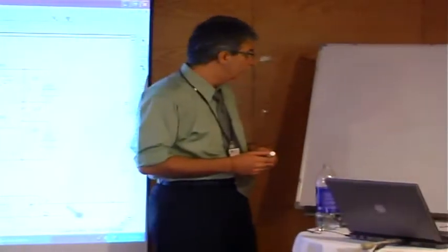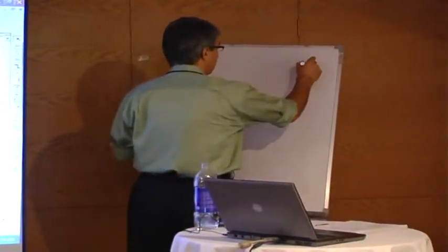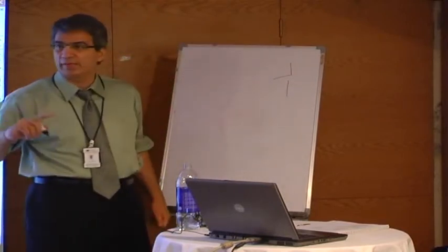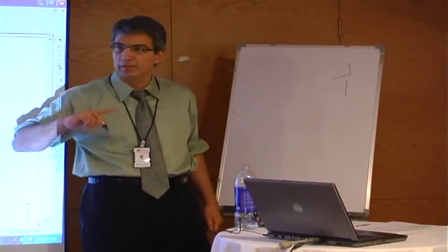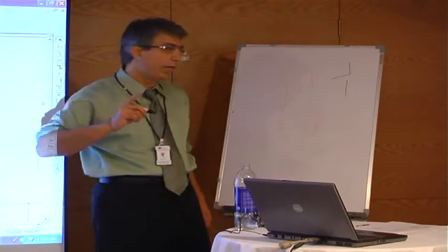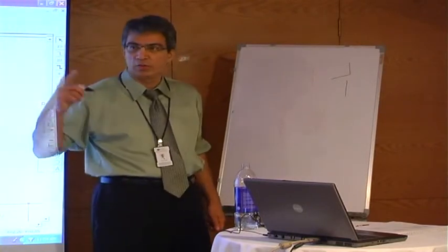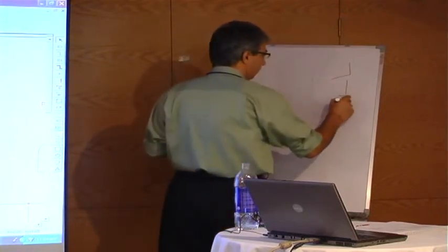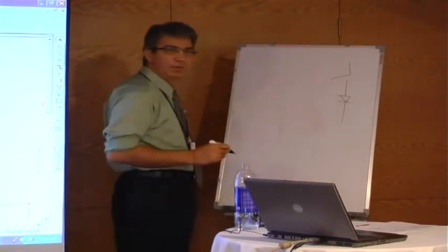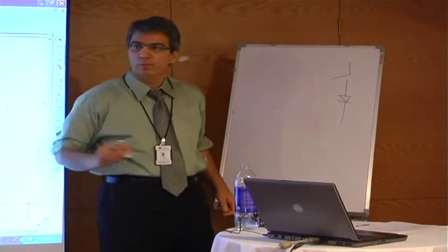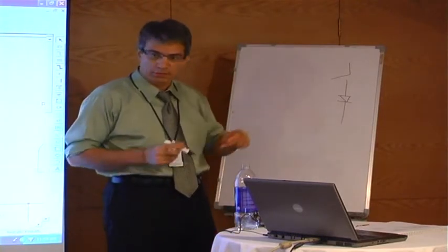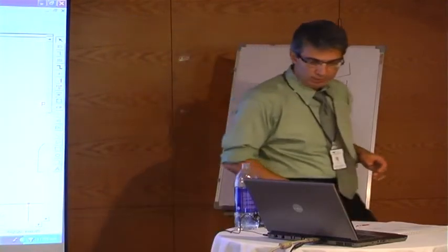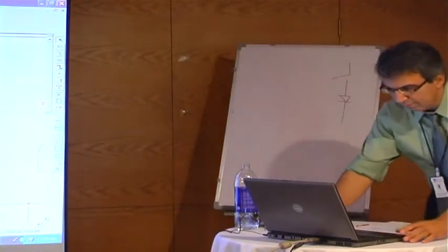Series. So let's say this is a MOSFET. A MOSFET is a bidirectional device, right? A MOSFET can switch back and forth. IGBT and BJT can only switch in one direction, right? So you can basically put a diode in series with the switch to include directionality. And let's look at the diode.